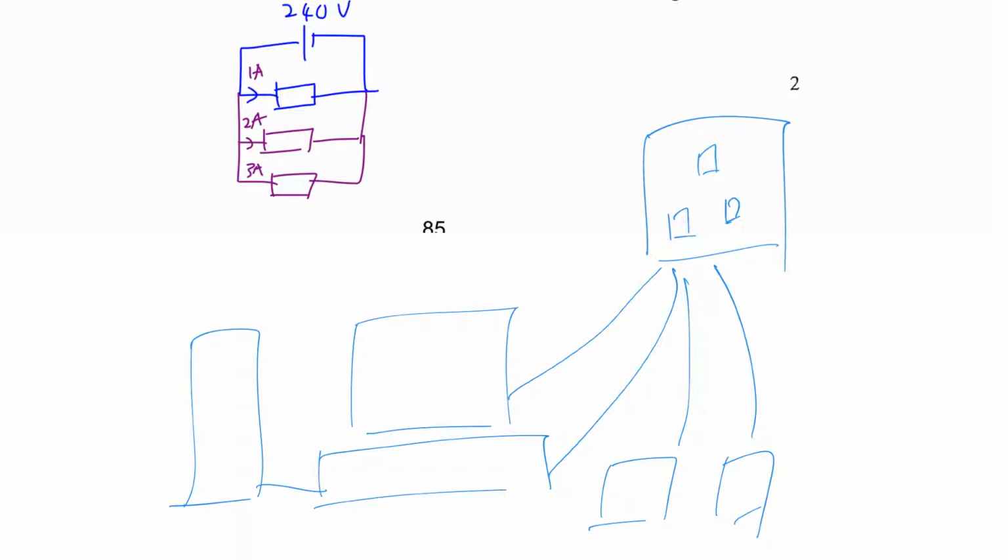All right, then you also connect to here. So every time you're connecting, right, are you connecting them in series or parallel? Now it has to be parallel. Why? Because it needs to function at 240 volts. You see, like for example in Malaysia, right, our household supply voltage is 240 volts AC. So all the appliances that they sell in Malaysia must operate on 240 volts AC. So therefore, every time you plug it in, you must be 240 volts supplied to your appliance.